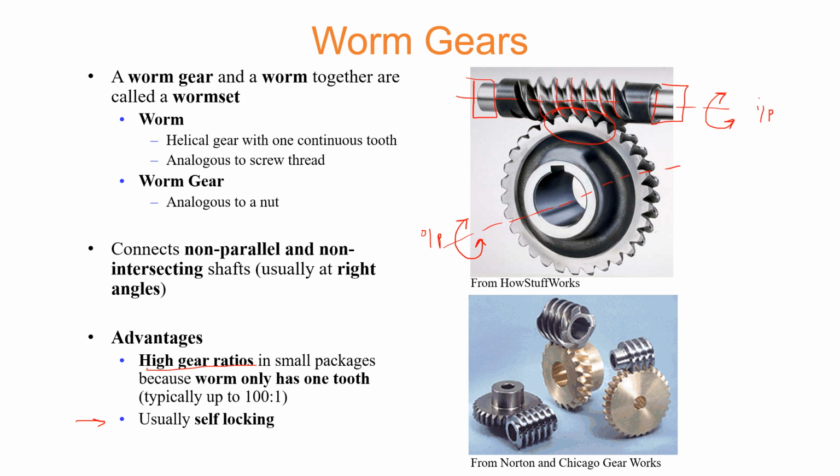This can be very advantageous because you can allow the motor to be momentarily powered off, and the worm gear itself is going to have some sort of locking arrangement, a kind of fail-safe arrangement, if I may say that, imparted. So that is a question that you have to explore further.